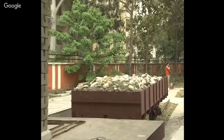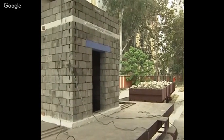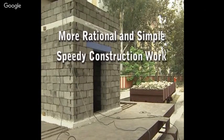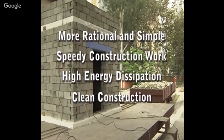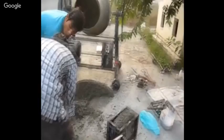Besides better earthquake resistance capacity, there are several other advantages of the interlinked block masonry system over the conventional masonry system. It is more rational and simple, supports speedy construction work, and has high energy dissipation capacity. Moreover, it leads to clean construction at the site, since the blocks may be cast either in a factory or at the site by using different types of locally available materials.